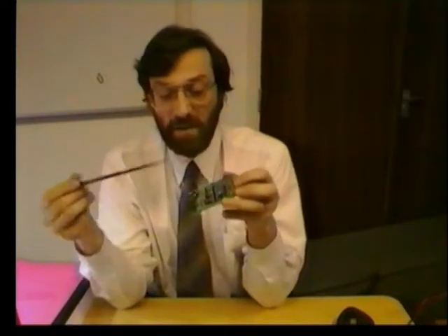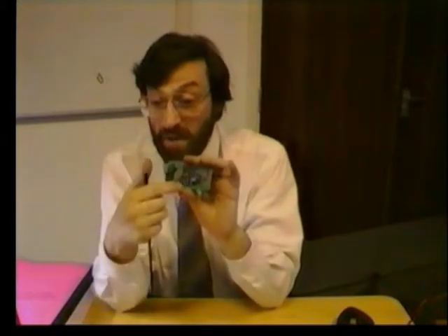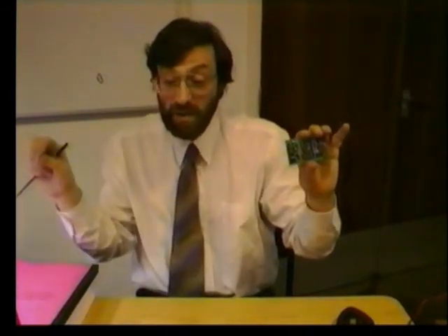What's really nice about it though, despite all this electronics here, the whole thing takes only 20 milliamps, which means it can run off a battery. So you can take your real-time system monitoring the temperature all the time, and you can put it in your harsh environment well away from you. You don't want to be anywhere near something that's that hot, but you can put the remote electronics there and it will transmit over a 2-wire transmitter to you the latest temperature information. And what's more, it will do all the corrections and maths for you as well, because you can get the most incredible amount of processing power out of these small microcontrollers, and it's doing it in real time. That is a real-time system.